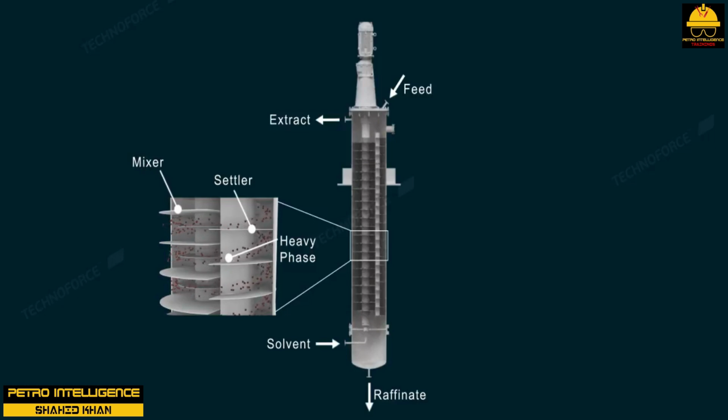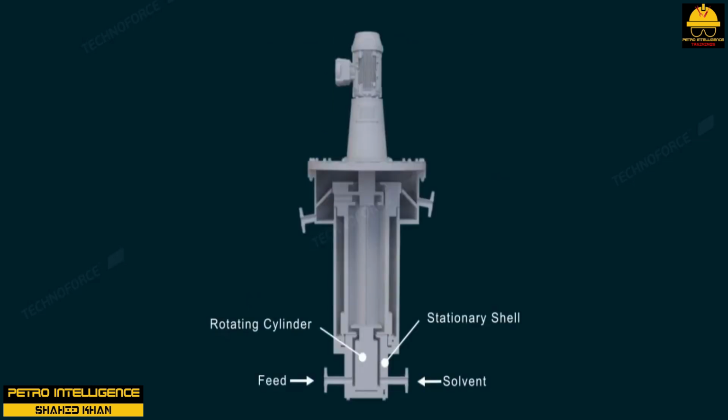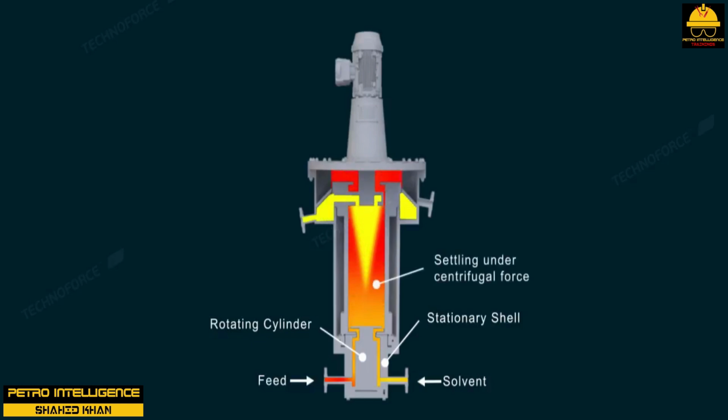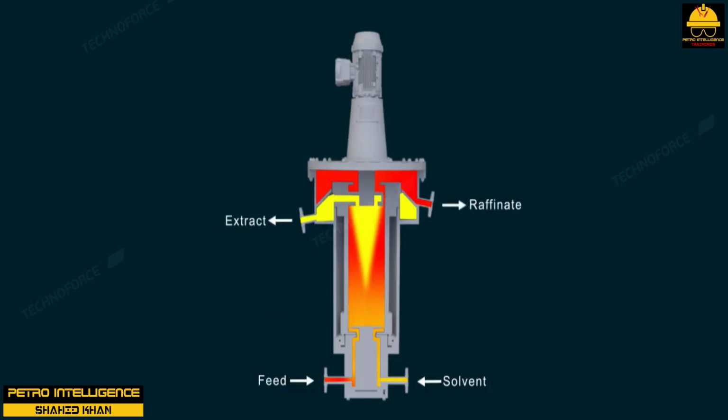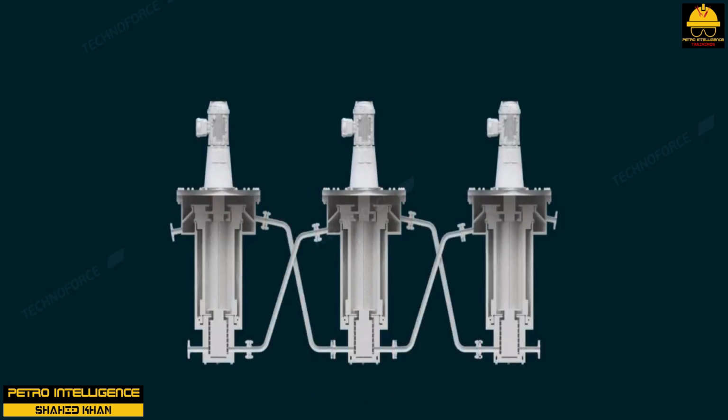In its simplest form, this could consist merely of a series of single-stage units, coupled close together. In this case, 3 stages are used, but obviously any number could be used. Notice that the solvent and feed both enter the system on the left and the raffinate and extract are removed at the right. The raffinate from each stage is the feed for the next stage, and the solvent for each stage is the extract from the preceding stage. Such a flow pattern is called concurrent, that is, the flows are in the same direction. In effect, such an arrangement is an attempt to use several stages to accomplish the separation that could be accomplished in a single stage with perfect mixing by remixing the materials again and again.